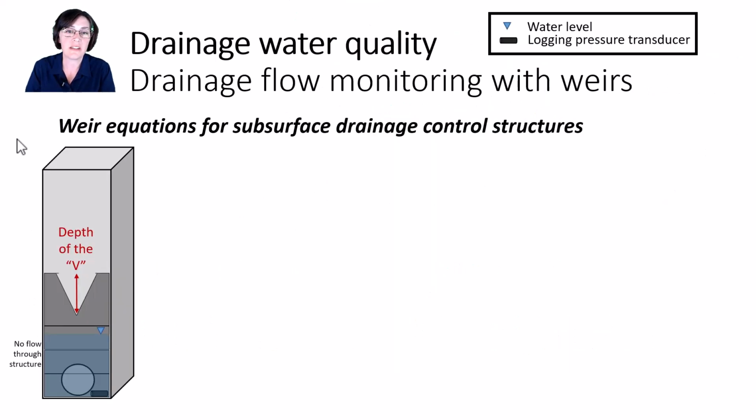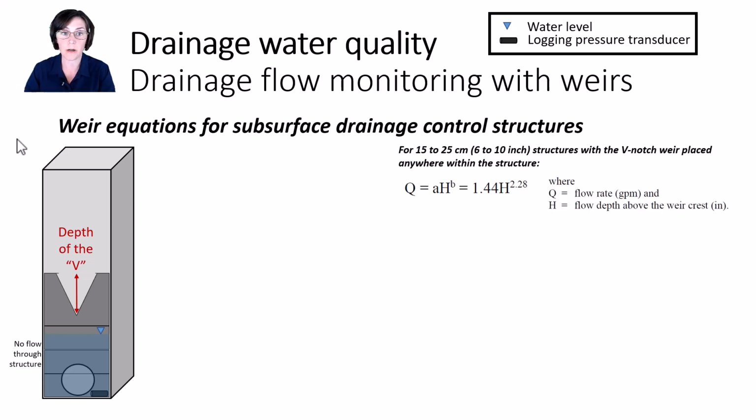I want to talk through the decision criteria for using the right weir equation at the right time in a control structure. These criteria are based on the water height above the stop log, which of course can vary day to day. Starting with the first scenario, the easiest one. The water depth you see illustrated is below the top of the stop logs. Clearly there is no flow, or put differently, the flow rate is 0. There's nothing going over that stop log weir.